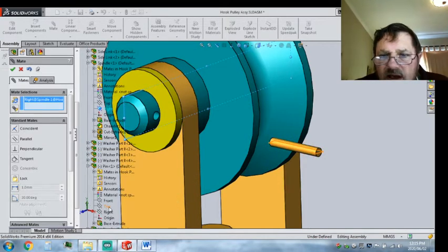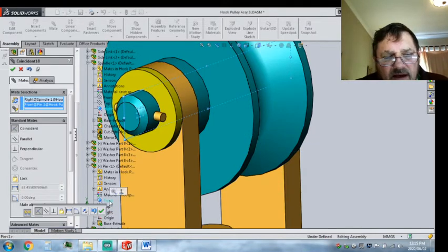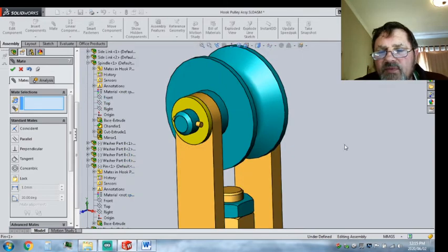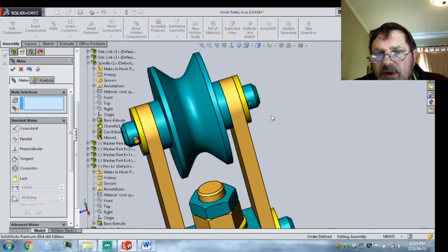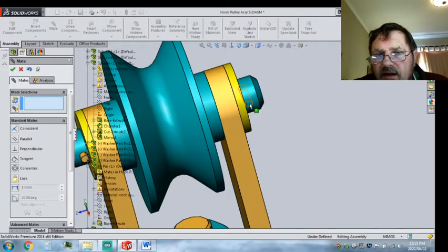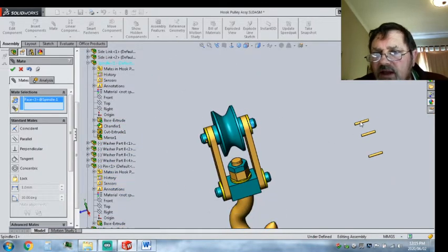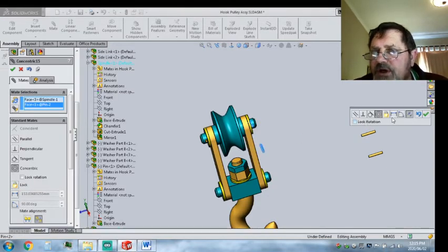Go check here. Let's go look for not that plane, front plane. So I made those 2 planes together. He's locked in the hole. I can take the green OK tick. Sorted him out. Now for my next mate, I'm going to take that surface. Be careful to choose the surface and not the edge. That one next. Yeah, I'm pretty sure he's okay.